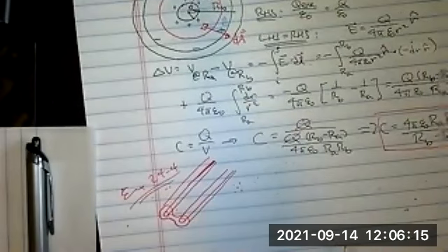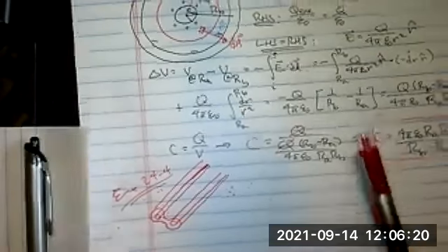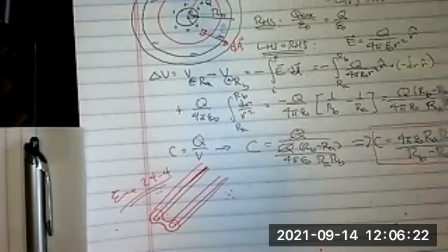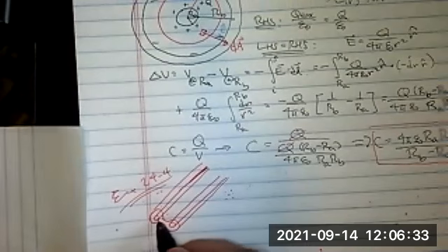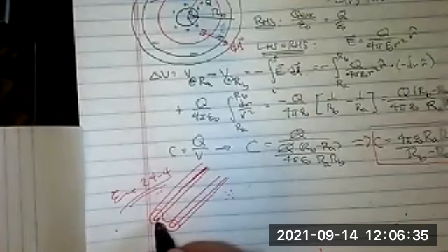So that is an actual real physical problem, because we're dealing with literally a wire that we could still use in principle for antenna wire, and you'd get a capacitance, say, per unit length or something like that. So by all means, check that example out. It's pretty straightforward. The one thing you got to realize is when you do the voltage, you're actually integrating from a distance lowercase r. If you call that radius of that wire lowercase r, you're integrating from there to a distance of d minus r. So you got to be careful with that.